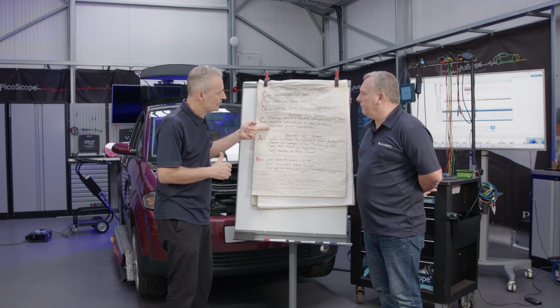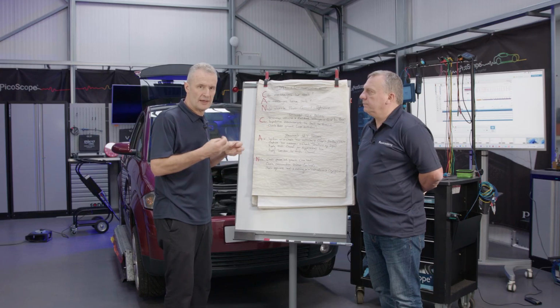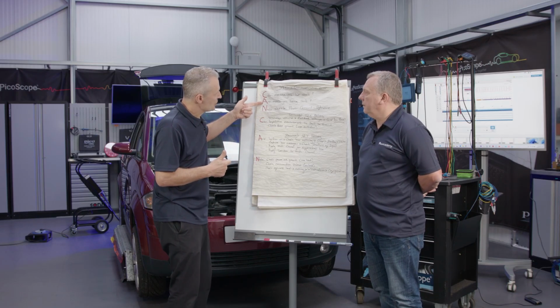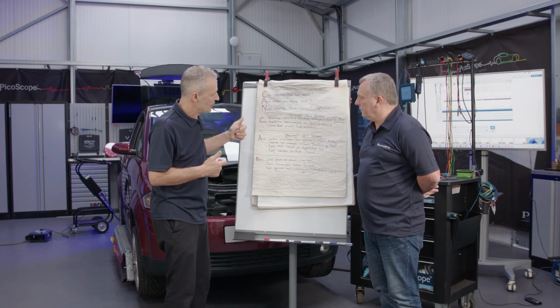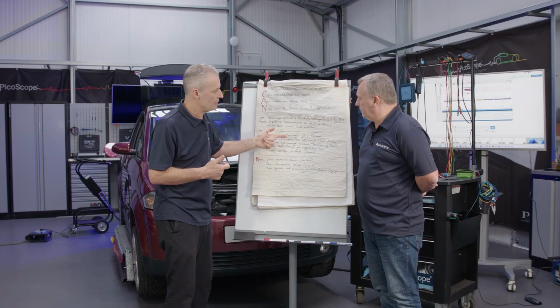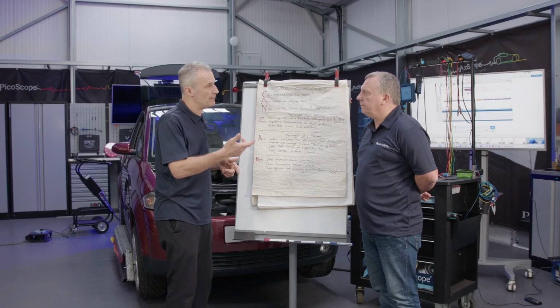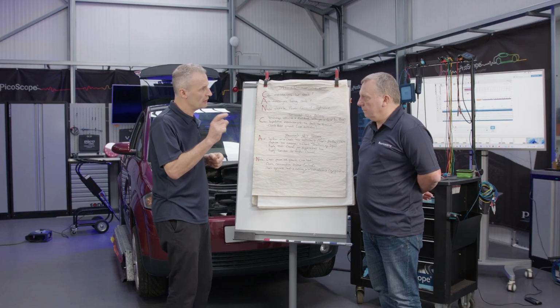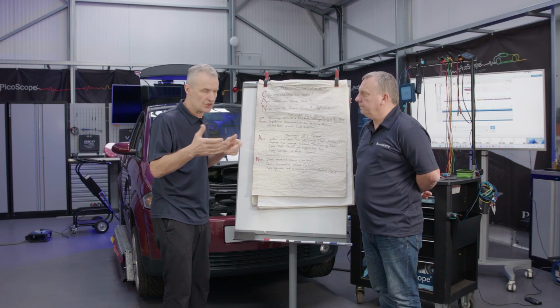I like this, checking node ground using milliohm. That was a way of loading the circuit when the vehicle was dead. Next was, are messages being sent? So ignition on, check bus activity. We went through the sleep, the standby, and captured the wake. Used two guided tests, if you remember. The first one was the physical layer, just looking at the structure of the signal.